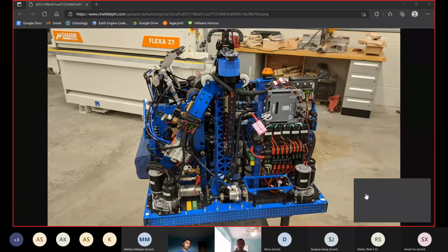More specifically for the Limelight, we still haven't fully done it because there are some issues with it. But it's meant for the vision tracking to aim the robot at the port, since no human can just pull up and shoot it directly. We used it during the Infinite Recharge challenges a lot, but I think it's a black and white feed that comes through, so you can't really use it for anything other than vision tracking of a light object or reflective object.